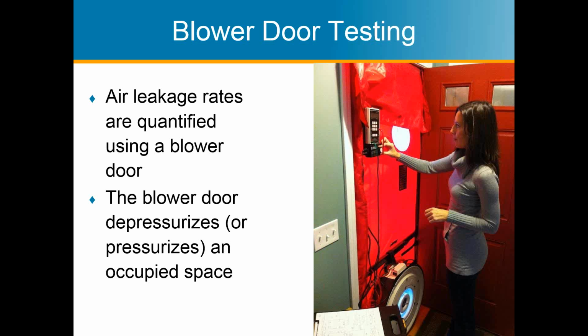There are a few rules of thumb that you can use to figure out the hole size, and these are very general. If you divide your blower door number by 10, that's the number of square inches if you took every little leak in the house and put it into one leak. So if 2,000 is your number, you've got a 200 square inch hole in the house.